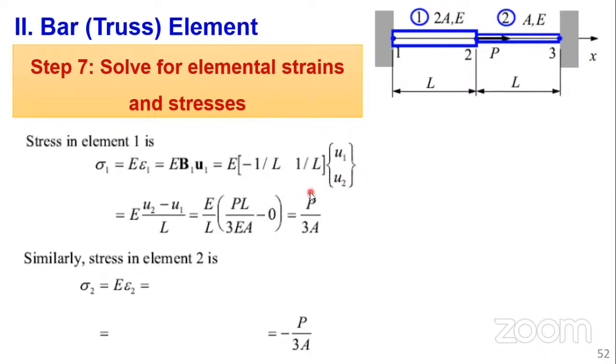And even if you use, what do you say, with this approach, even if you use the mechanical materials, strength of materials approach, you are still going to get the same. I know you know the stress for a bar element is equal to P over A. So this tells you that the value you have computed using the approximation method, which is the finite element method, is exact, or is the same within the linear theory.